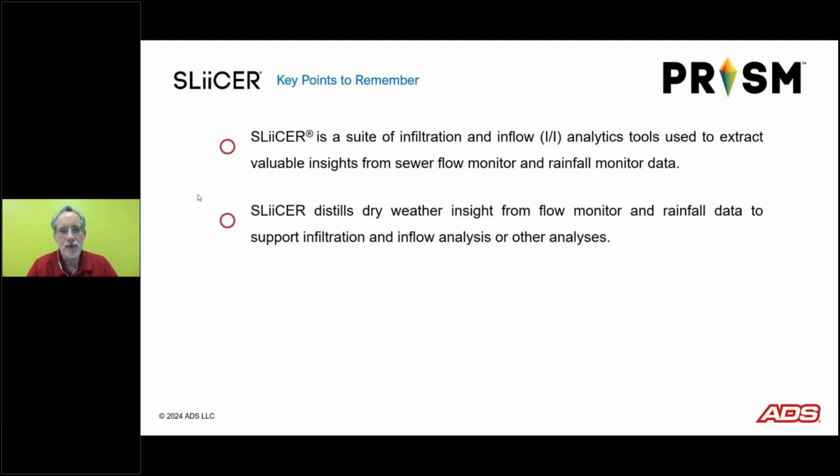And in terms of the dry weather, we can distill that dry weather information. We can slice it out of the data, if you will, to support I&I analysis or other analyses. So if you're doing some capacity analysis work, you might be looking at dry weather flows. You can get that out of SLiiCER.